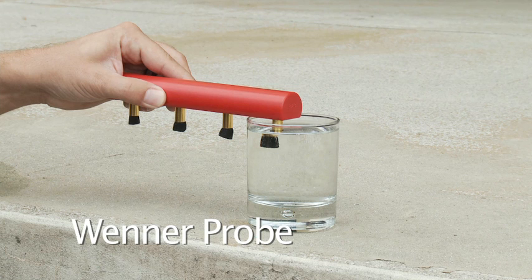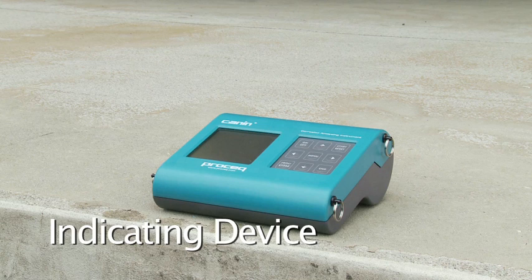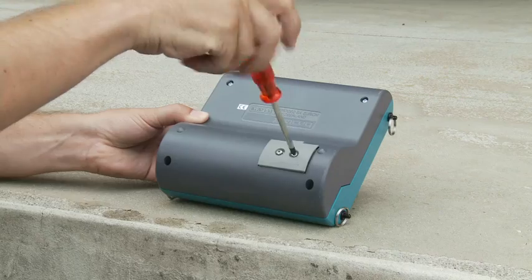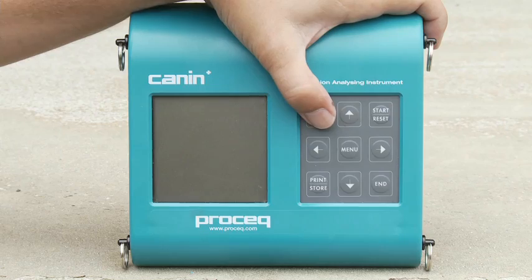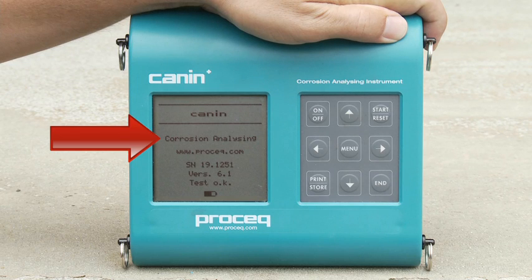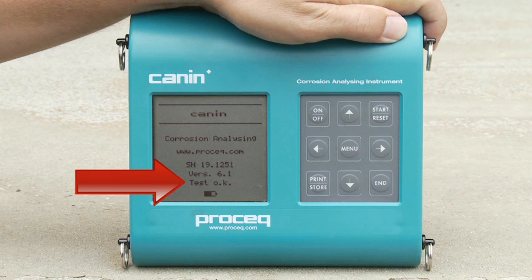To prepare the Wenner probe, each of the 4 foam pads should be moistened with water. Now to the indicating device. Use a screwdriver to open the battery compartment and insert the 6 batteries, checking for correct polarity. Then close the battery compartment. Press the on-off key. The following data is briefly displayed: the operating mode, either corrosion analyzing or electrical resistivity meter, the instrument serial number, the installed software version, and whether the automatic self-test is OK. There is also an indication of the battery status.